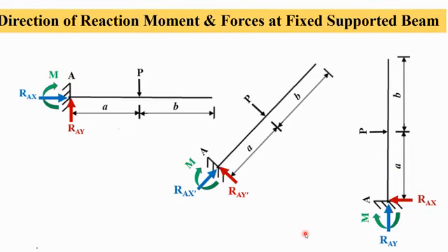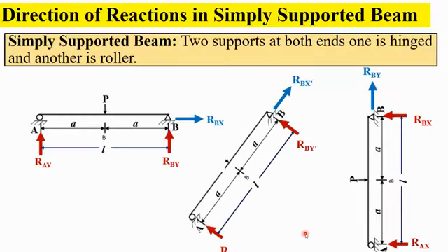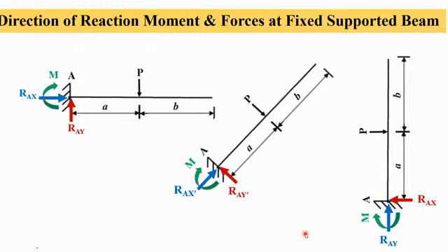That was a simply supported beam. Now, if it is a cantilever beam, three reaction forces will work on the support. Fixed support. A cantilever beam has a fixed support. One is vertical, one is horizontal, and one is moment. I'll explain this moment. If it is inclined, again similar. One is along the plane, along the longitudinal axis, one is perpendicular to the longitudinal axis, and the moment remains the same. It doesn't make a difference if it is inclined.